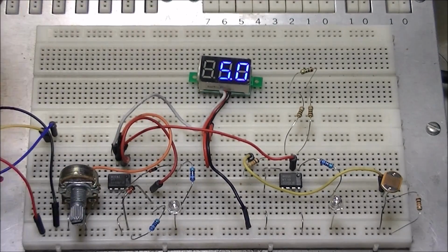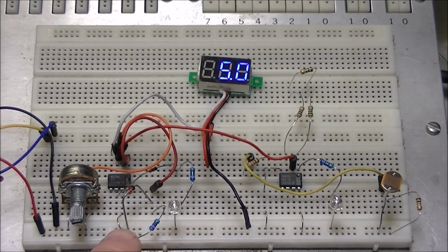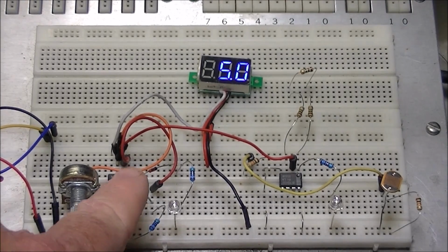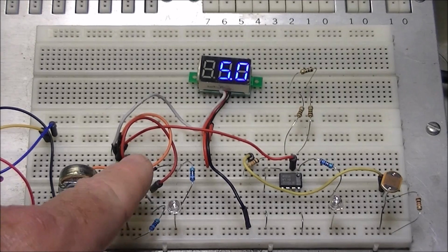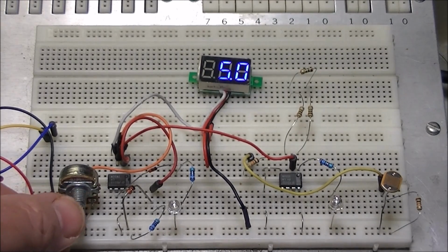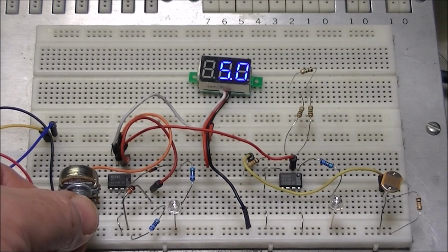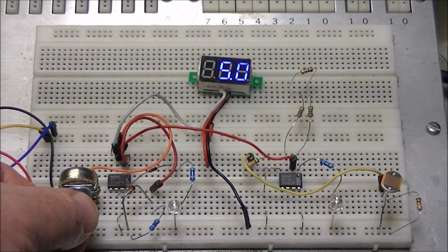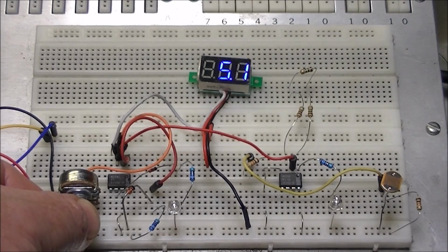Look at your readout here. Over here is about a 6 volt Zener diode, if you can see it. So that's going to be my reference voltage for the 741 op-amp. And if the voltage going on what I call VN in the schematic, voltage in, exceeds a certain value, you notice the LED comes on.